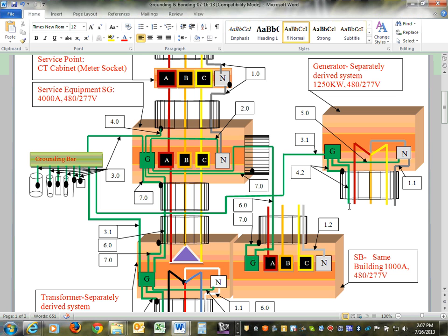If your enclosure is part of your generator, then everything is bonded inside the generator. Then you take a wire from where your circuit breaker on the generator is located all the way back to the panel or to the auto transfer switch. That wire, after you go through the circuit breaker at the generator, the wire downstream becomes the equipment grounding conductor. Very, very clear.